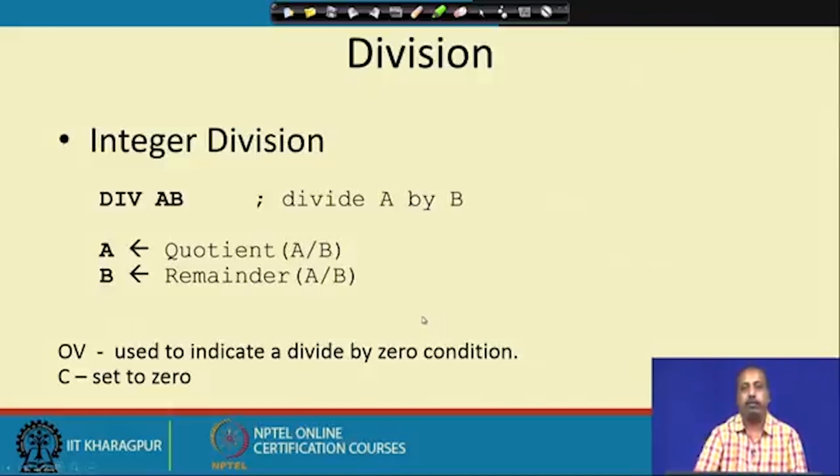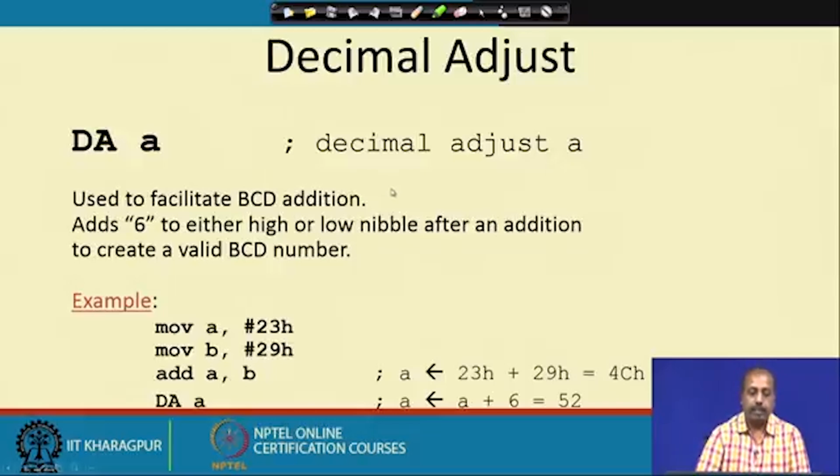If you remember 8085, we do not have any multiplication or division operation in 8085, but in 8051 we have multiplication and division, though only 8-bit in nature. If you want a larger multiplication, you have to follow some multiplication algorithm by which you multiply 8-bit numbers at a time. Each 8-bit number can be considered as a digit, and accordingly you can try to devise a multiplication and division algorithm.